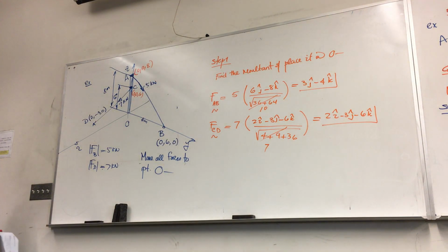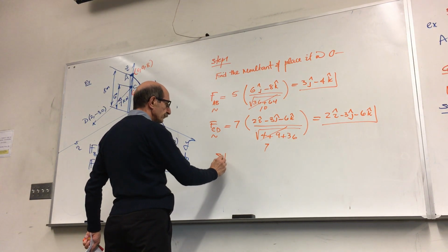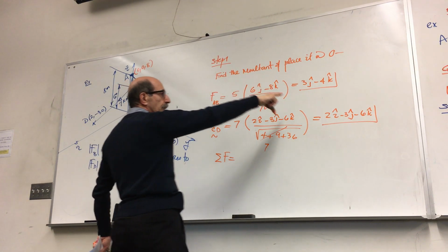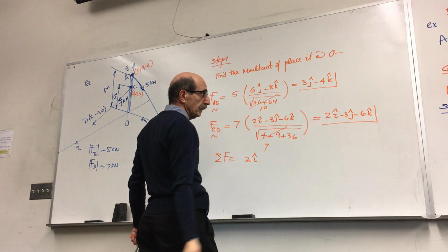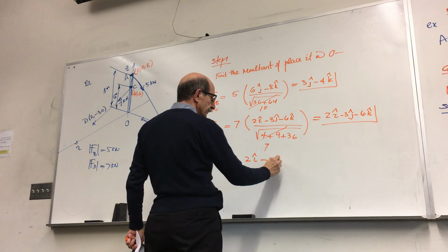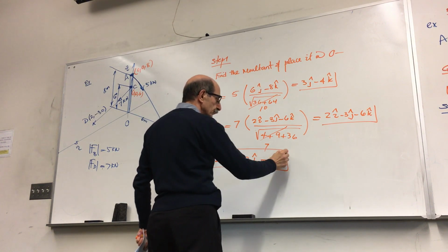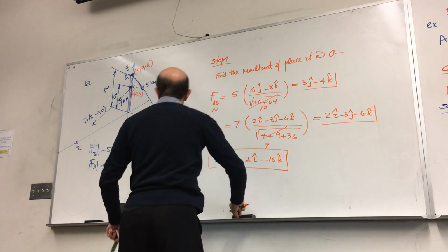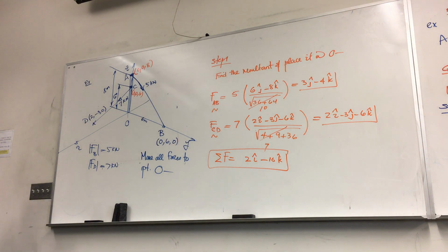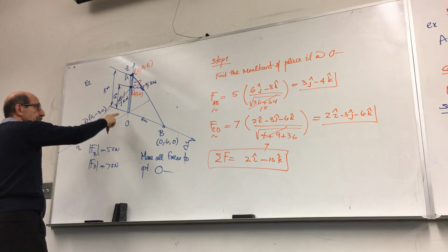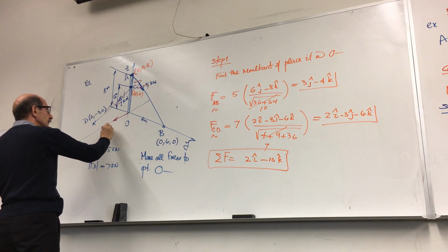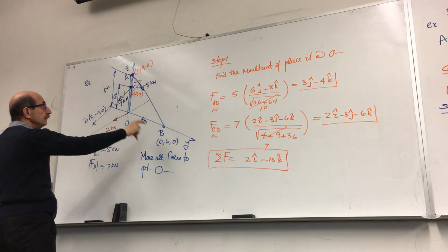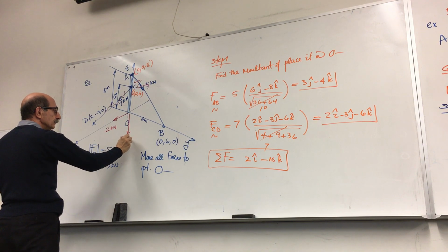Okay. So the resultant is what? Resultant, sum of forces. Just add them up, right? So you have 2I. Okay, 3J and 3J cancel out, so I have minus 10K. So that is the resultant force, which means you just simply remove those forces, right? Put the resultant here, and that resultant is a 2 kilonewton here, and negative 10, meaning a 10 kilonewton here.